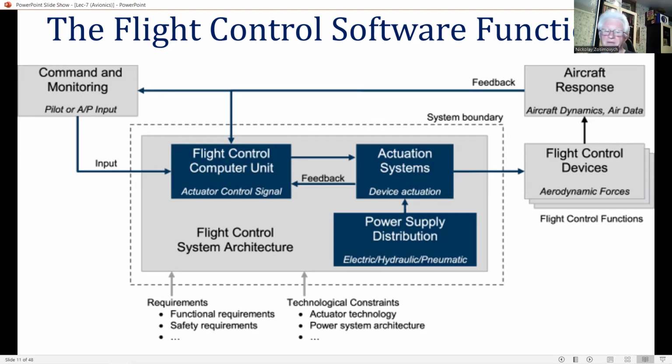Redundancy management can account for between 60 to 70% of the total software. In the case of a modern civil FBW aircraft, the proportion is generally not quite so high. In a military FBW aircraft, it's around 50% for a modern agile fighter.